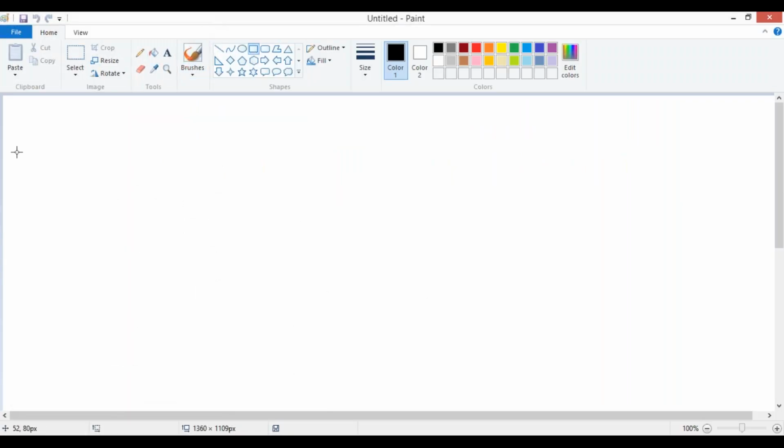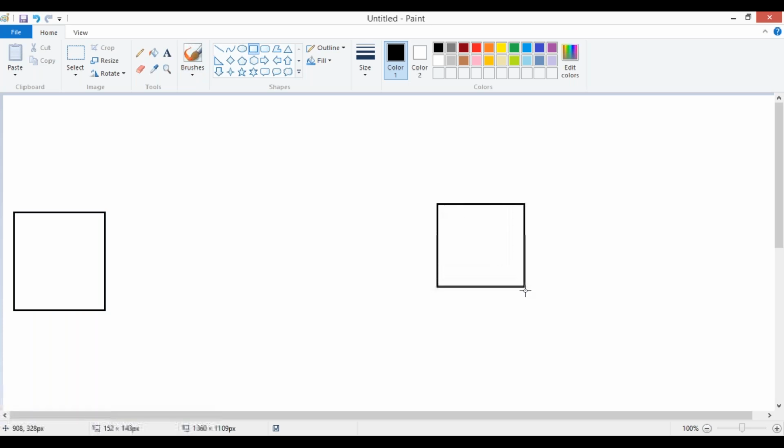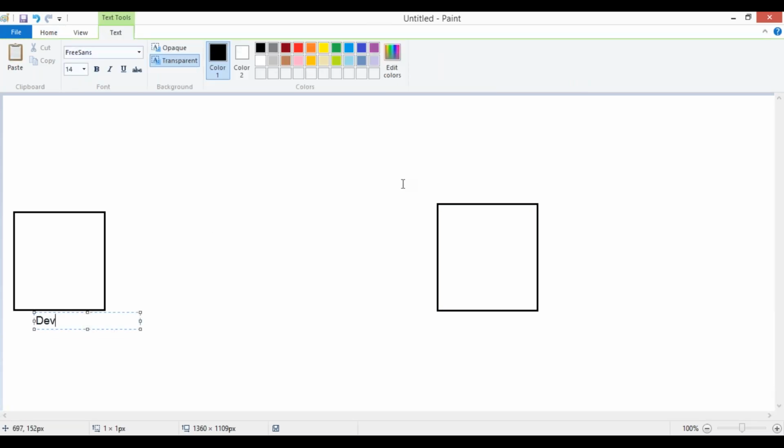Okay. So let's say you are doing communication between two devices. UART is what kind of protocol, interboard or intraboard? It's an interboard protocol, right? So you can communicate between two different boards. Let's say this is my device one, and this is another device two.